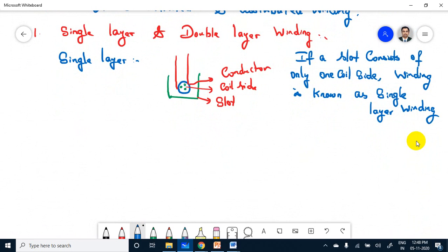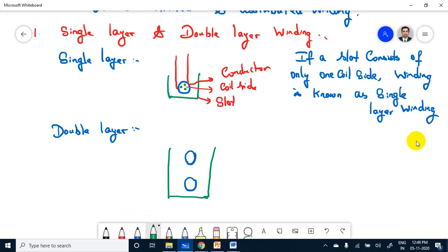So now I compare the double layer winding with the synthesis equation of the Fourier series. Here omega naught is pi. This is conductor 1 and this is conductor 2. What is the K value? Both conductors are connected as j k omega naught, so if you compare, K is 2.